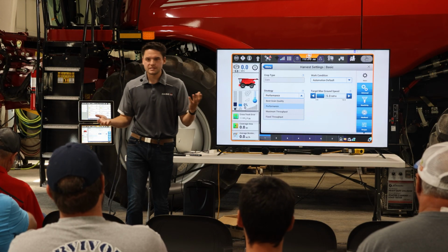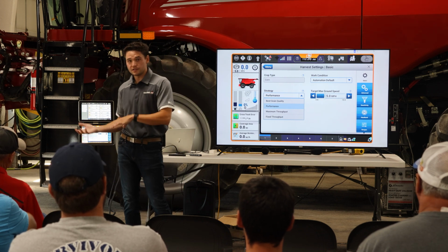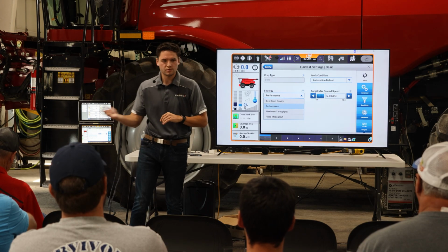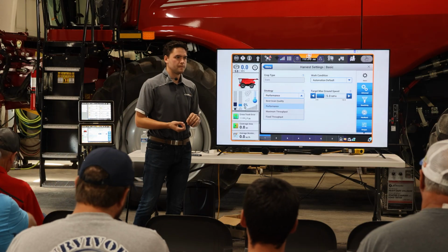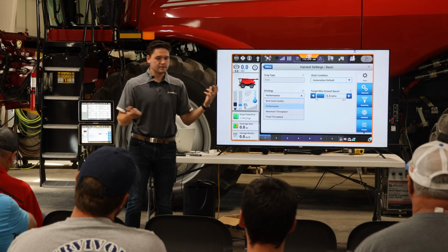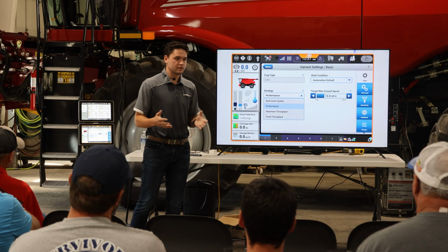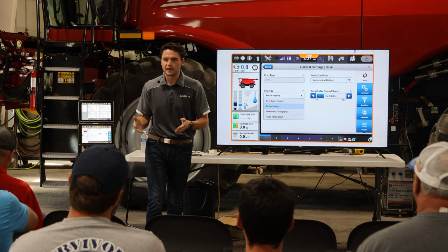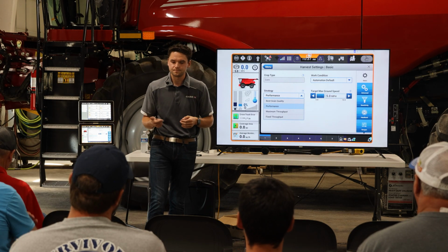But there are a few things that maybe we aren't aware of what happens in the background when we do that, maybe some prioritizations the machine will take when we select performance or best grain quality. So we'll just take a minute and go over it, and then with that knowledge you can decide what you want to do. So best grain quality is, I think, pretty self-explanatory. Its main priority, its main focus, is to produce the best grain sample possible. So as minimal broken grain and as minimal MOG as possible.